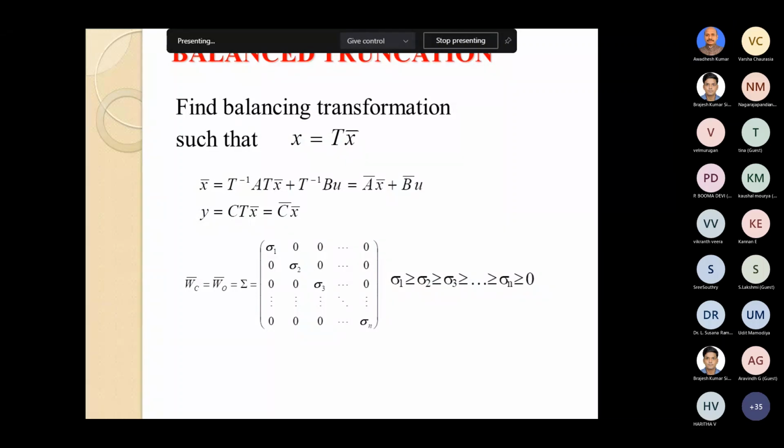So in the balance truncation also, we have done the projection based methods we were continuing, and we have done the Krylov method. Then another projection based method is truncated balance realization or balanced truncation method. This is one of the alternative methods for model order reduction of linear time invariant systems. This method is basically based on singular value decomposition. One has to understand what singular value decomposition is first, and then we will be able to appreciate this method more.